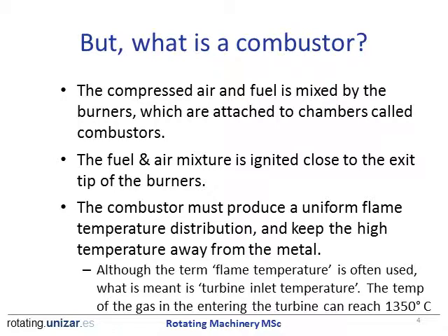What we are really concerned with is the turbine inlet temperature, because the temperature of the gases that enter the turbine is what gives you an idea of the energy that is in this hot gas. So this is the temperature that we mean. Even when you hear talk about flame temperature, most of the time people mean turbine inlet temperature. And to give you an idea, we are in areas close to 1350 degrees Celsius. This is where technology more or less is moving now.